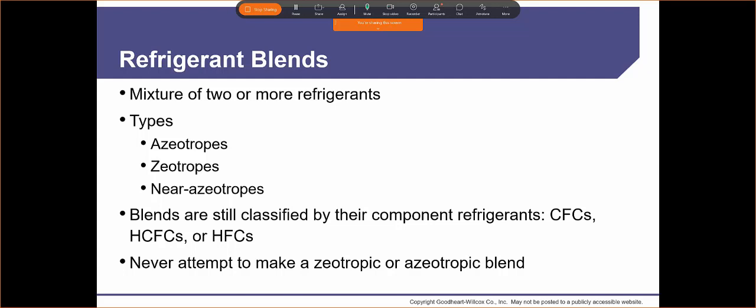So what we do is we take our tank and invert it, so it's upside down. As we start to release the refrigerant into our system, we're charging it as a liquid. That liquid travels up through our gauges, and we throttle our gauges so the refrigerant coming up to them is a liquid, and as it exits our gauges, it's going to flash, and then go into the system.